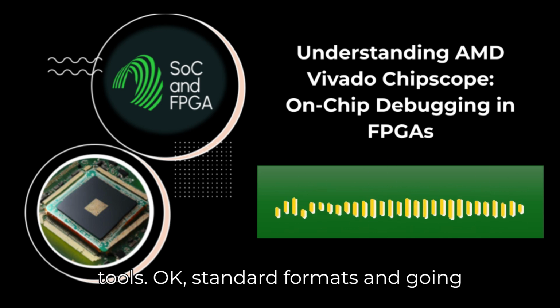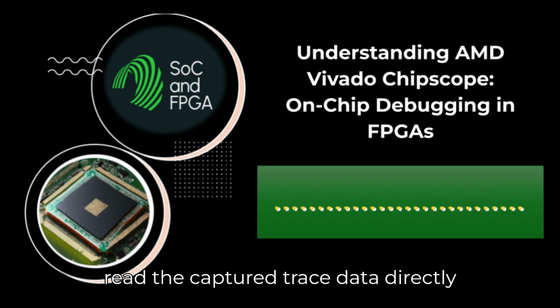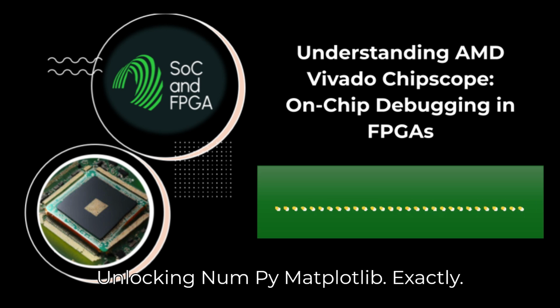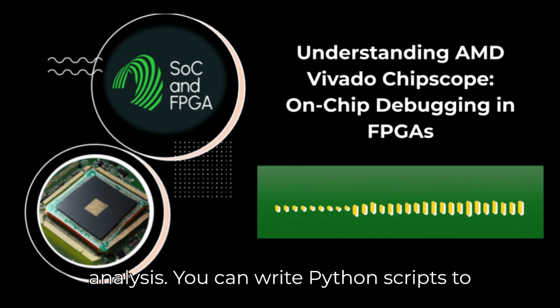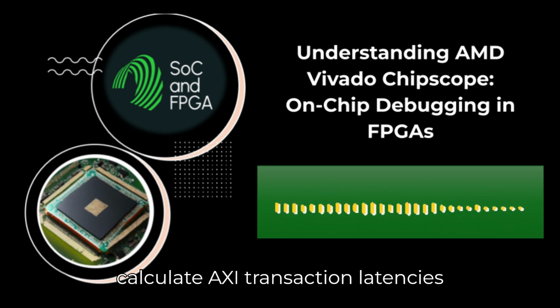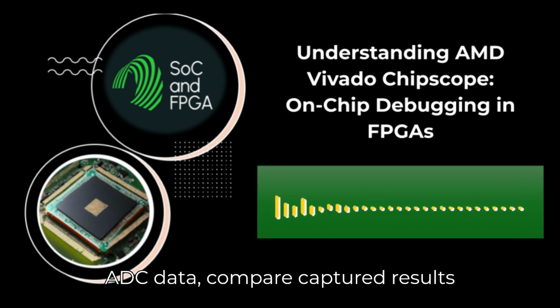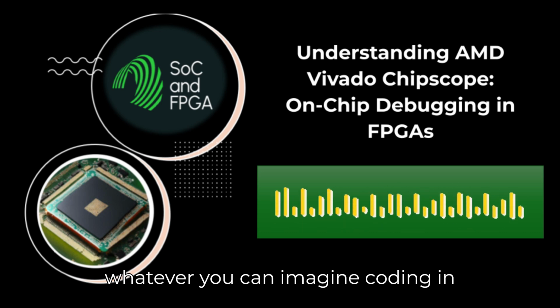Okay, standard formats. And going back to Chipscope, the Python API lets you read the captured trace data directly into a Python environment. Right, unlocking NumPy, Matplotlib. Exactly. This opens the door to limitless custom analysis. You can write Python scripts to calculate AXI transaction latencies automatically, perform FFTs on captured ADC data, compare captured results against a golden reference model, whatever you can imagine coding in Python.